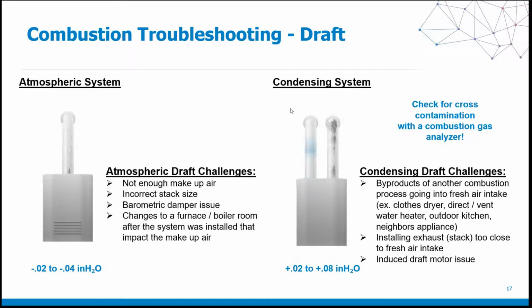When we talk about cross-contamination, a lot of technicians are not aware that a combustion analyzer can actually solve that issue for you. The way that you do that is very simple, and that is by measuring the quality of the fresh air intake that you have, because that fresh air should be 20.9%. If it's not, and it's anything lower than that, you have cross-contamination. And that's one of the other things that we cover, again, more extensively in our training programs, but that's just something to keep in mind. And it's a feature that a lot of people don't know an analyzer can perform for you.